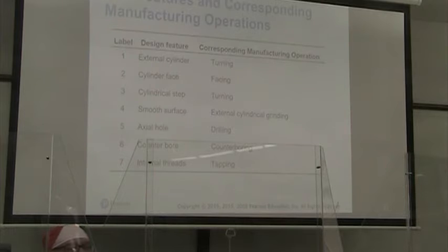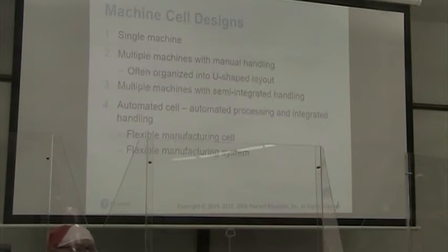Right, so you'll notice that you've got 2 turning operations. You have a facing operation. A grinding operation, essentially 2 drilling operations, because drilling and counterboring are much the same, and a tapping operation.